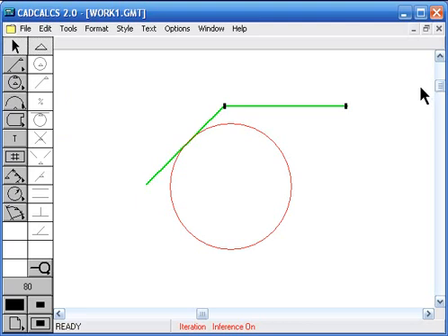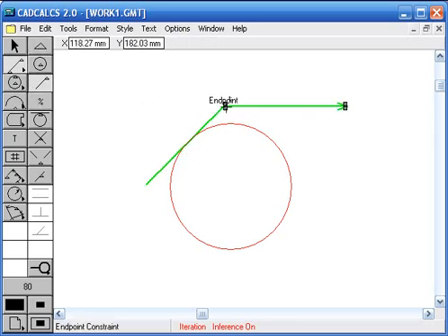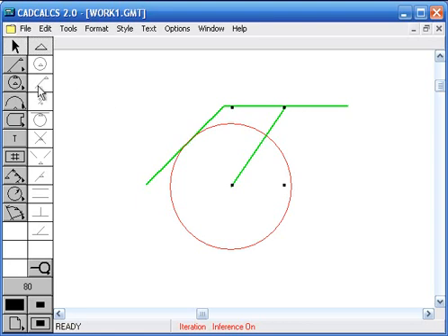That's the step one method. That means you are using the noun and the verb and then the modifier, and then you're creating the constraint. So you're constraining it on the fly. The second way is to infer the constraint. So what I do is I select the line tool and it'll infer the points for me. I want the first point to be at the center of this circle and the next point at the midpoint here. I want to create a line which starts from here and is tangent to this circle.